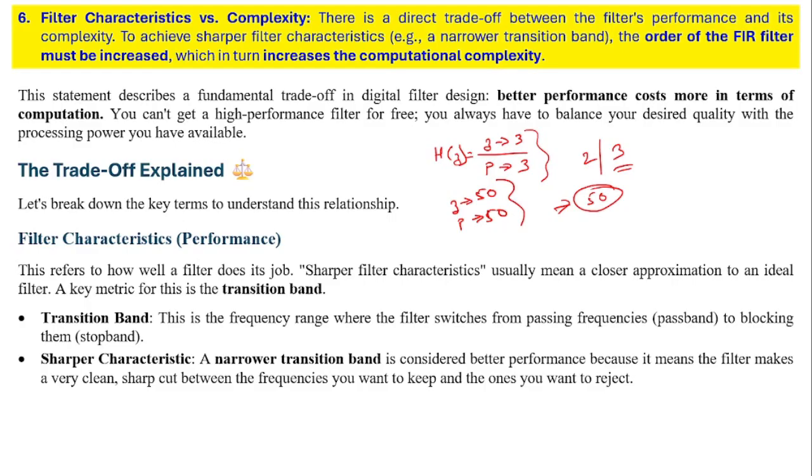So we can design a linear phase response in the FIR filter. But that is not possible in the IIR filter, because the placement of the poles and the zeros are related to each other, and it becomes very difficult to get both amplitude response and phase response to an optimal level. So we have to come to a trade-off.